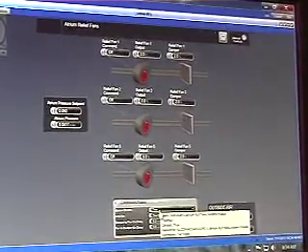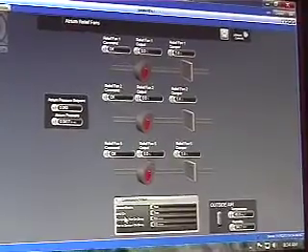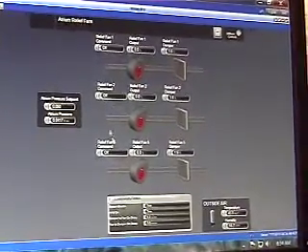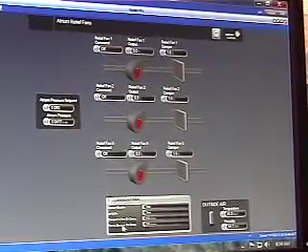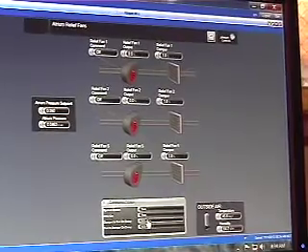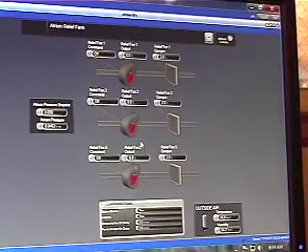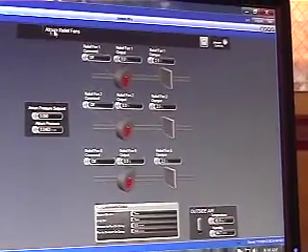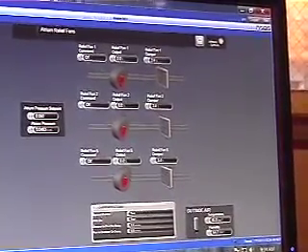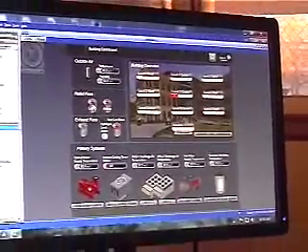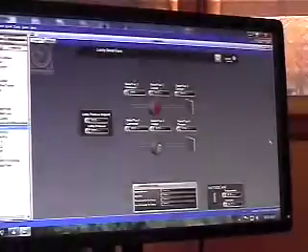Down here you have a system enable if you just need to shut it down, operate override that faults. AHU is on. That's the link from the air handler letting you know that the air handler is running, so the fan system is enabled. And then you have your damper to fan on delay and your fan to damper on delay. These are just your transition points from when we turn the fans on and off. So 1, 2, and 5 are tied to the atrium, and on the other one, the lobby, is the other 2.